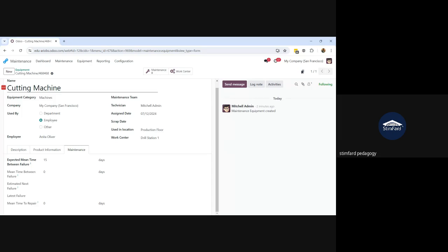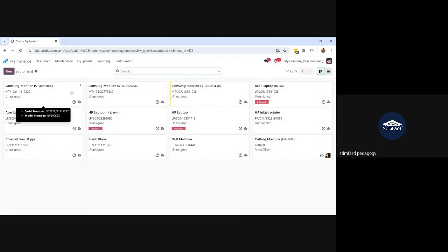So if this is a new machine, you will only be giving the corrective maintenance, and by the passage of time, if it has become an old machine, you will have the historic data of the machine: how many maintenance requests are coming for that machine, and when it needs planned maintenance. Or if you are getting a new machine, there is a booklet, like when we purchase a new vehicle, they recommend that after every 3 months or after every 6 months you have to do the tuning work or the special maintenance for that vehicle. So you can plan the maintenance according to those schedules or according to the manual of that machine.